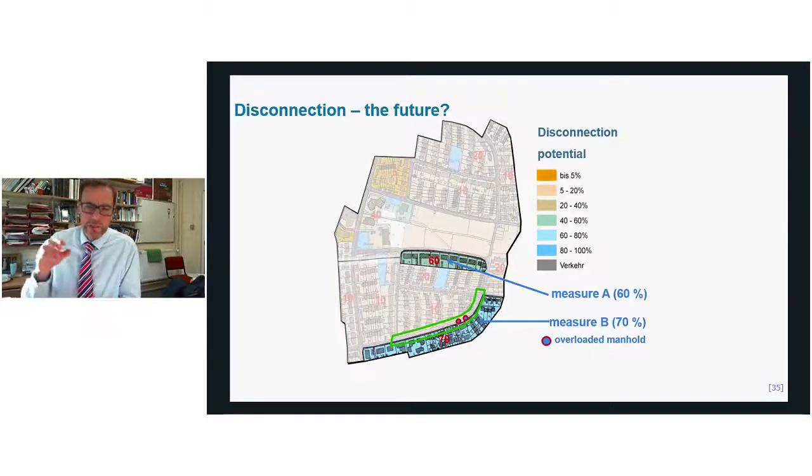So it's not about disconnecting, say, a large car park from a combined network to stop that surface water going into the combined network and creating a new surface water pipe to take that to a watercourse. It's about disconnecting that large car park and then perhaps directing that flow to a pond or a basin where it's controlled quite locally. So it's no longer about transporting flows away and getting them into watercourses as quickly as possible. It's about how we disconnect those surfaces.